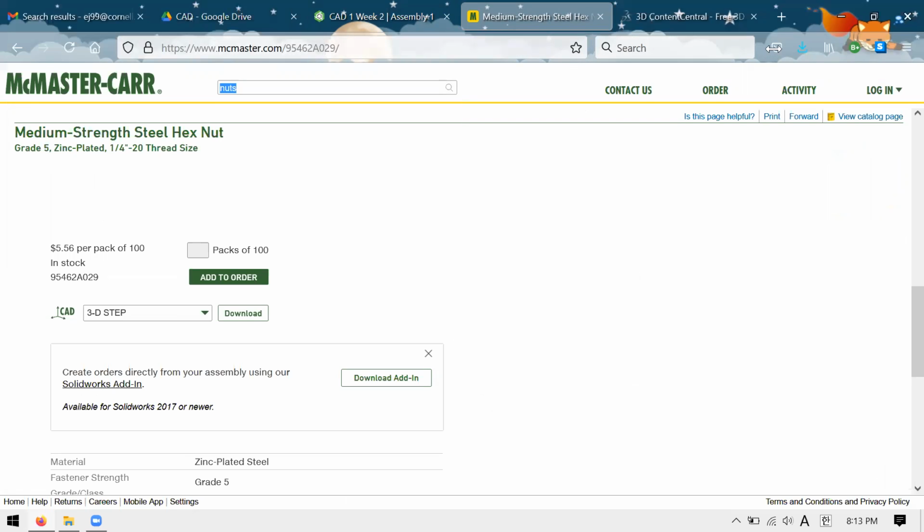So even for a single joint, the ball bearing inside might have some very precise, very strange diameter. Instead of trying to figure that out from data sheets to model a sphere, you'd just download the entire CV joint off of wherever you're getting it from, hopefully, and that's how you do it.